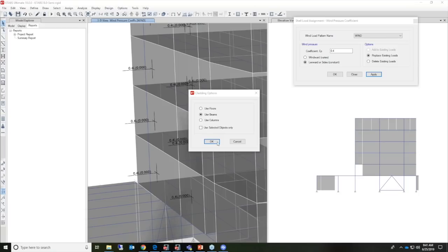If you assign a load pattern to create all sets, the program will actually create 12 load sets for the ASCE code, and they will be included in the same load case, which will have 12 different answers, each one of them considered as a separate case. And when they are used for design purposes, each one of them is used in the load combinations for design.